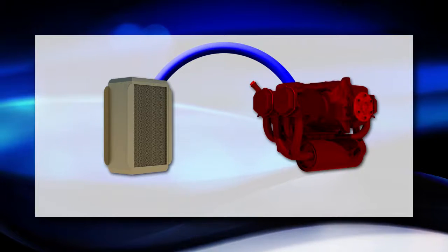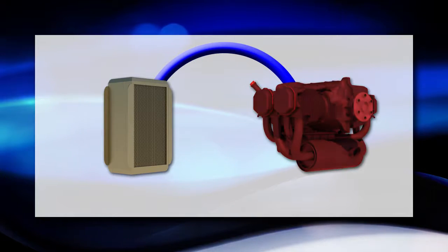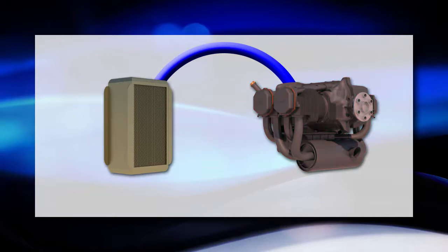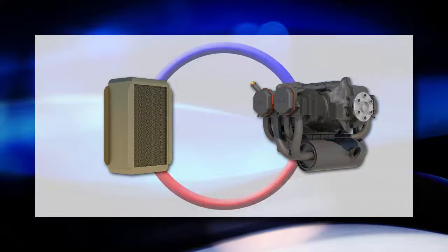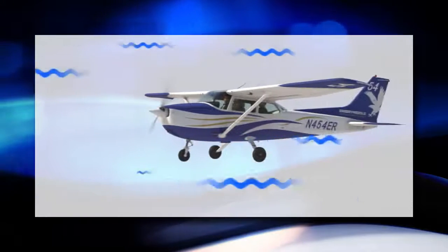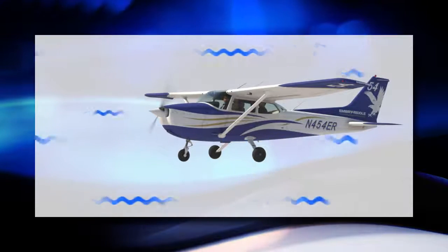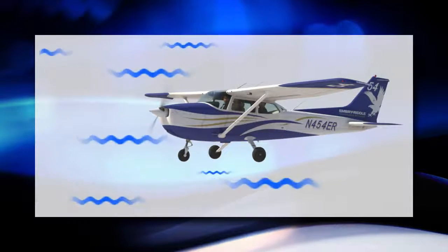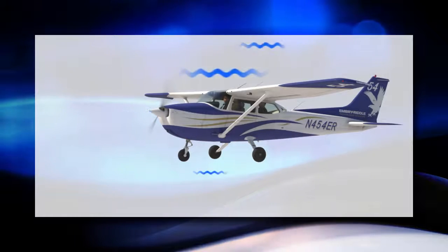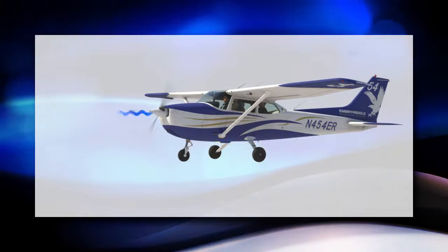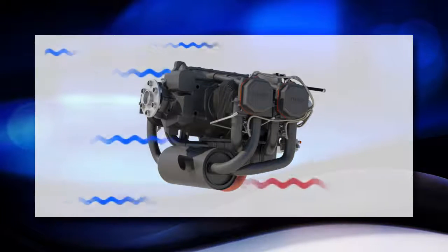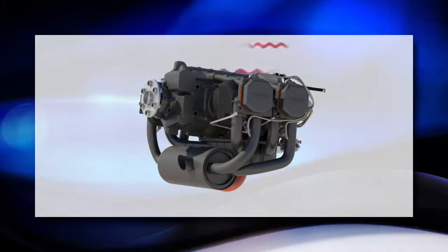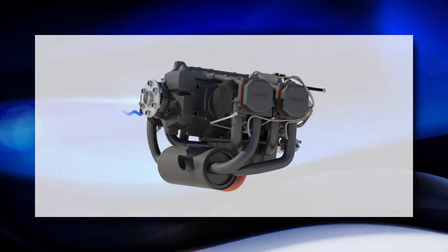As the cool oil touches the hot engine, there is a heat exchange, meaning that the oil becomes warmer, but the engine cooler. Then the oil returns back to the oil filter and oil cooler, and the process starts over. However, we also use air to cool our engines. As the airplane flies through the air, outside air flows through inlets usually found on the front of the airplane like the Cessna 172. This outside air is colder than the engine, so as the air flows over the engine, it cools it in the same manner that the oil cools the engine.